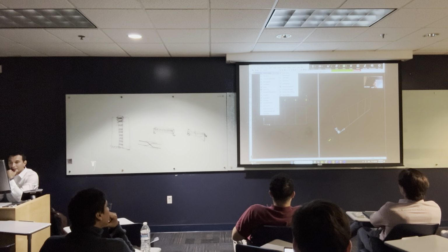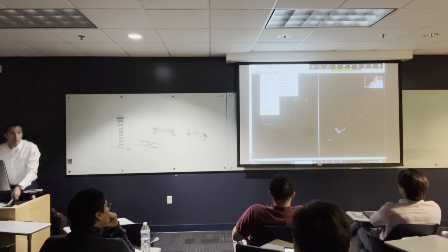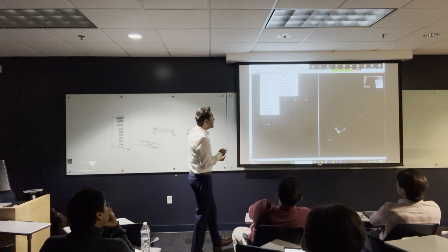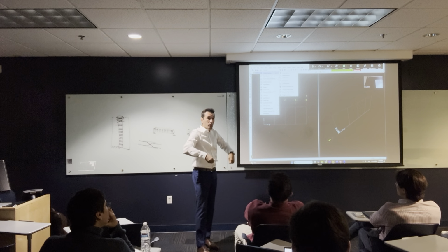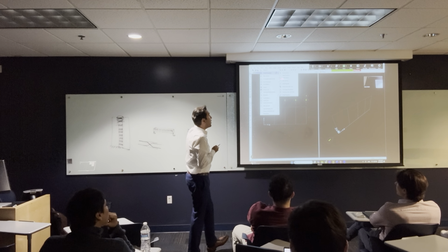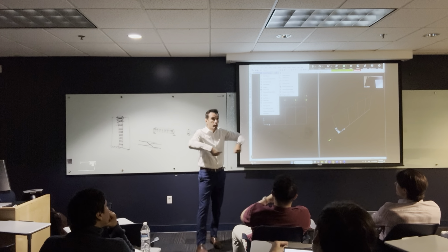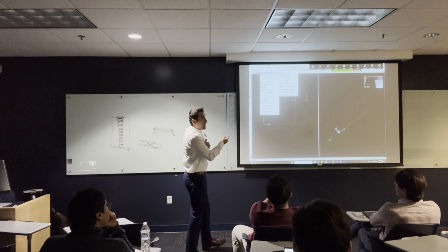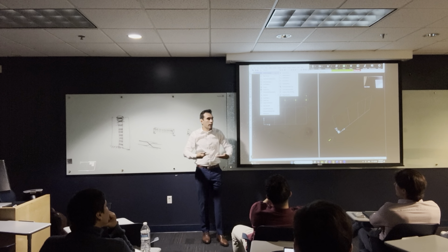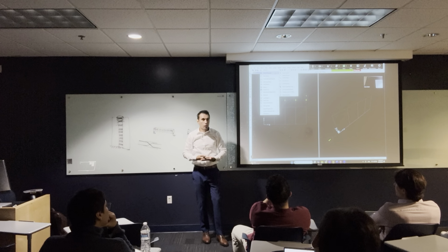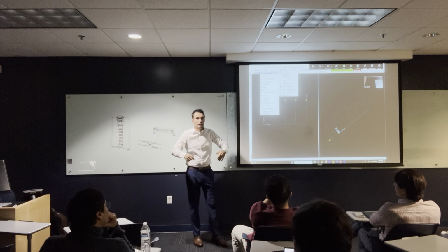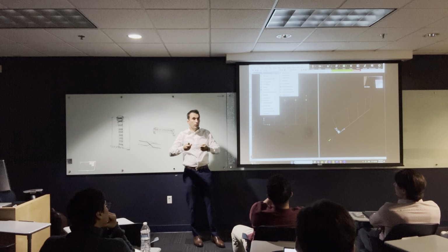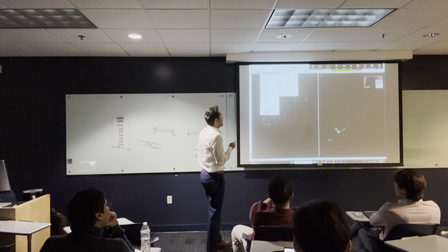Let's define cross sections. When you go to define cross sections, you are going to find multiple things to define. You are going to find frame sections, and you are going to find tendon sections. If you are going to do prestressed concrete or something, you have to define the cross section of the wire. Or you might have a cable, like one of the cable structures that we saw. The difference between tendon and cable: the tendon is the one that you put in post-tensioned or prestressed concrete. But if you have a cable-stayed bridge or a suspension bridge, you use a cable, so you have to define the section of the cable.